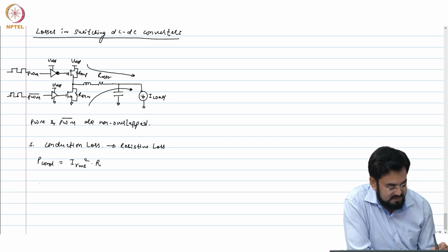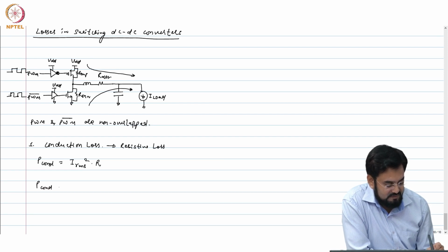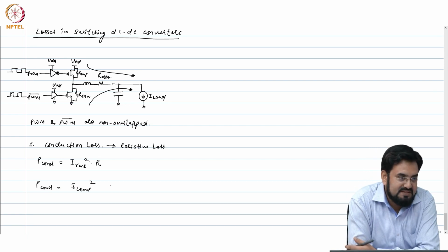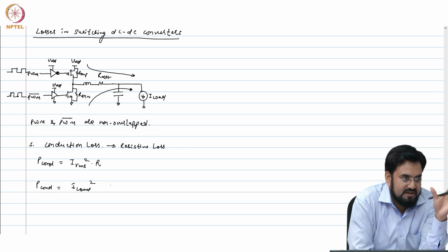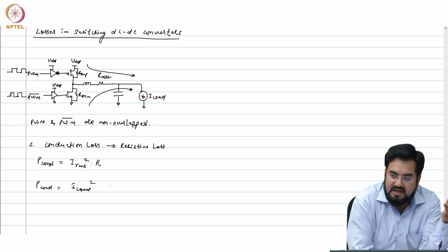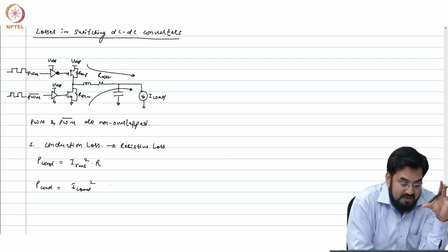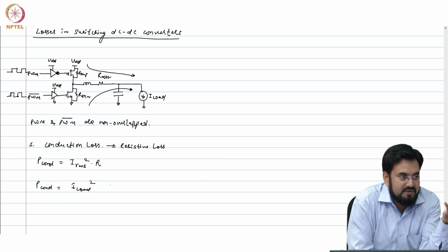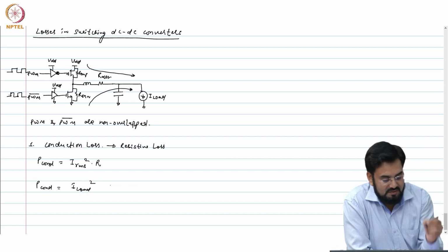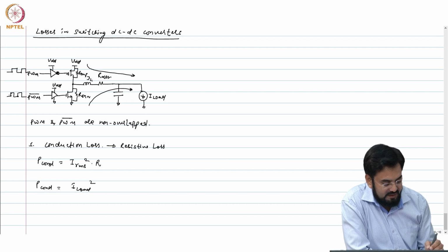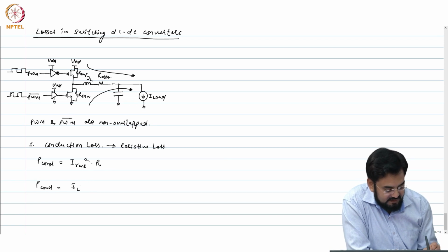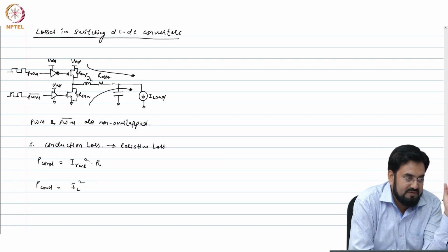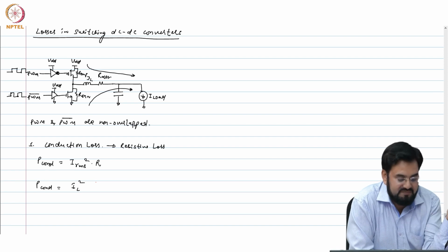What was the total loss? I load square. So RMS is pretty close to that if your ripple current is very low, then you can ignore it, so your RMS will basically be the same as your load current. But if your ripple is large, then you cannot assume I load, and you'll have to take the ripple into account as well. So if I call it IL, then better to write IL rather than I load. Where IL will have an average of the load current plus a ripple on top of it. Okay.